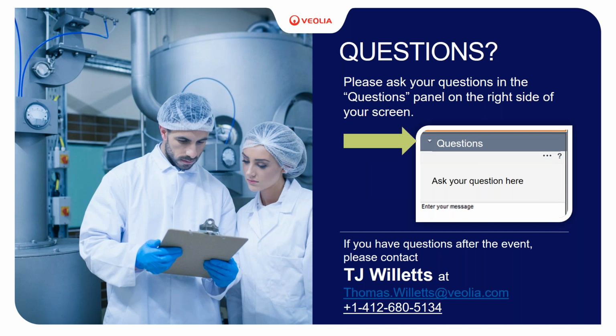And a follow-up question to that, Jill, is it common for sites to ship their sludge to be tested with their specific sludge? I think you mean sludge with chemical. That's not necessary. We have a bucket of fresh sludge that we keep in our lab, so we would expose that chemical to that sludge that we know to be good. We can also test sludge if you send us a sludge sample and do an activity test on it.